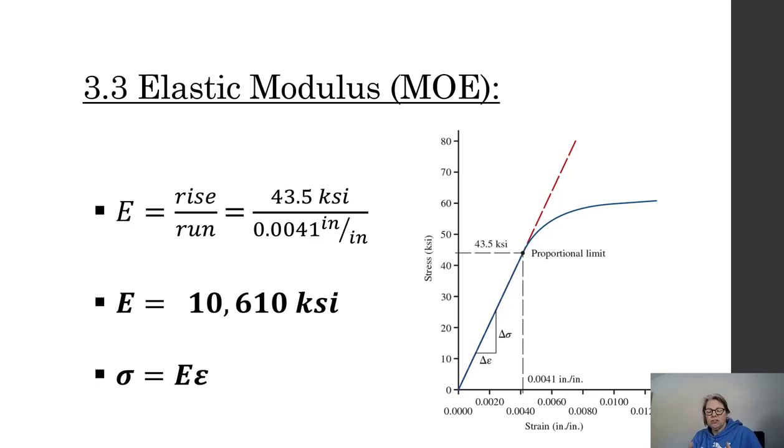When we did the strain chapter, we just told you it rotates 2 degrees. Its change in length is this much. Its strain is this much. Now we could do all the same problems, but we could make them statics problems where you have to find the force in the cable. And once you find the force in the cable, then you can use Young's modulus of elasticity to find the deformation. Stress equals E times strain in the elastic region.